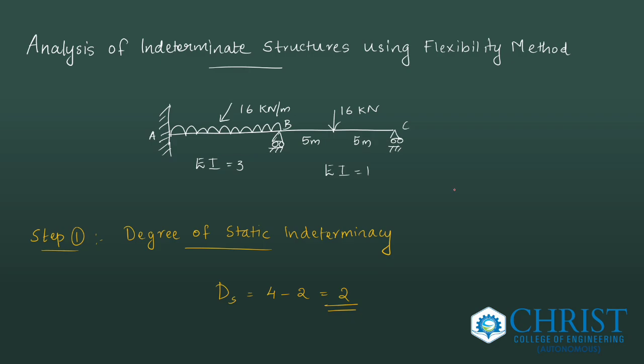That is, first we will define the system coordinates for external load and find the matrix. Then after which we will apply the redundant forces and then find the force transformation matrix. That's the difference. So let's see, the question is given, a continuous beam is given. We can clearly see it is an indeterminate beam for the flexibility matrix method, also called the force method of analysis.